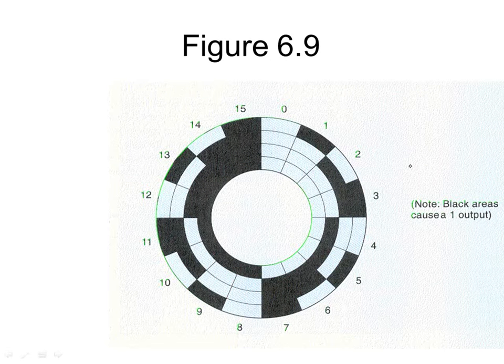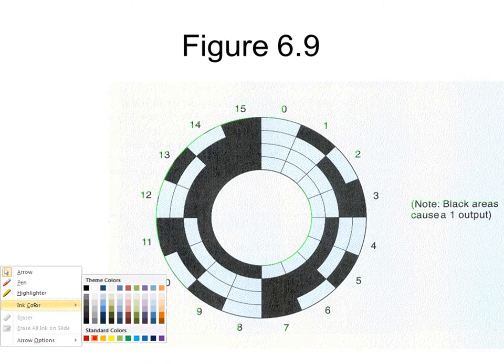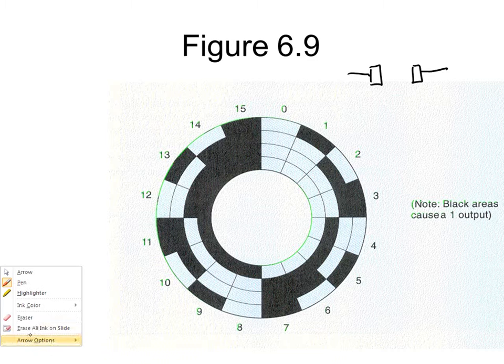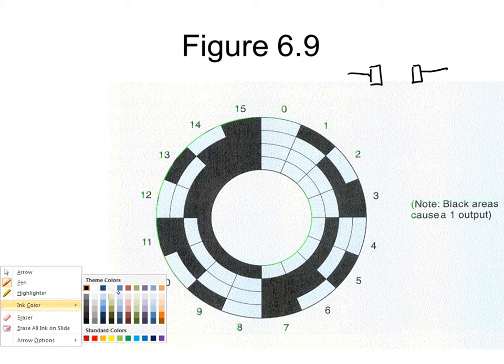We'll look at later on what we refer to as a through-the-beam sensor, which is an optical photoelectric sensor, where we have a transmitter that sends light, and a receiver that detects light, and we're shooting a beam between the two.